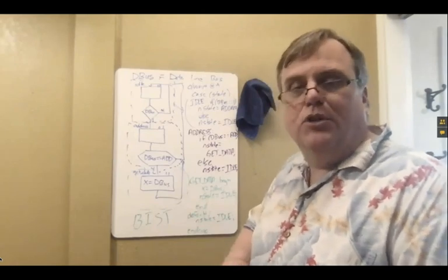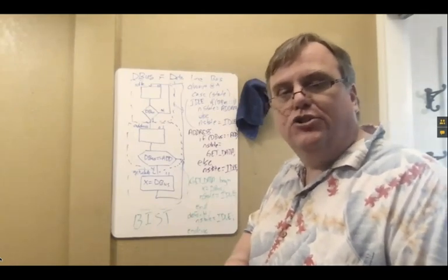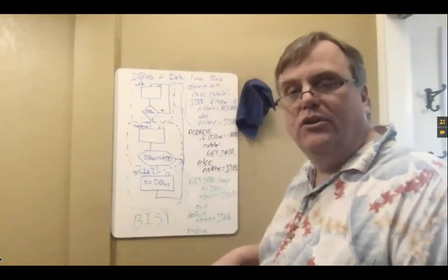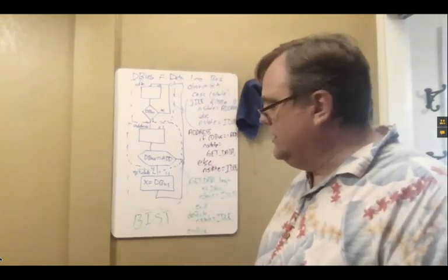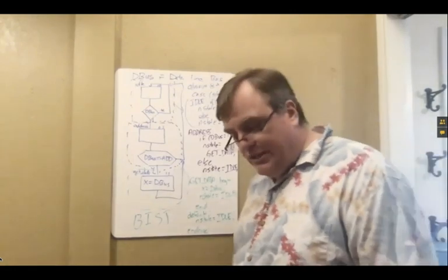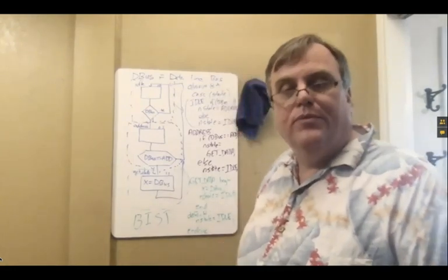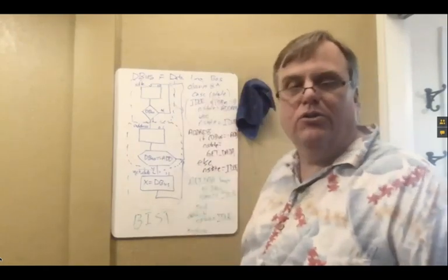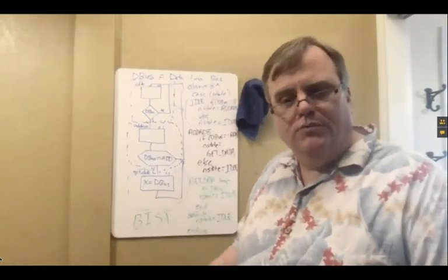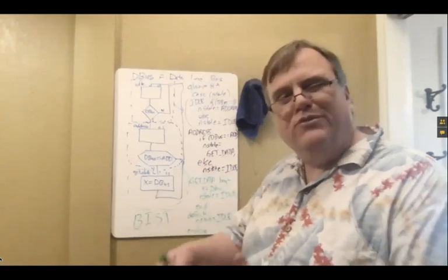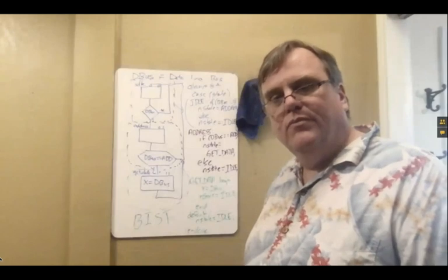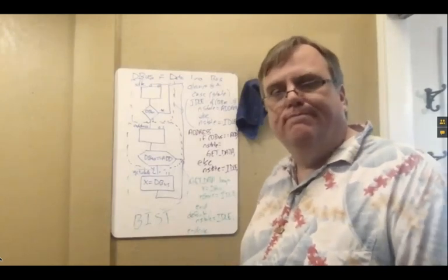With a built-in self-test, I might go, uh-oh, I ended up in a weird state. Could there be something wrong with my hardware? I should check this before going back to my idle state. I might run the built-in self-test to see, because there could be something fixable, and then go back to idle. That would be a nicer version. So I might want to do some amount of testing or checking if I end up at these weird states.